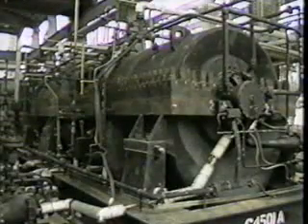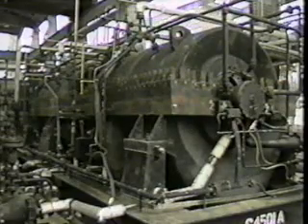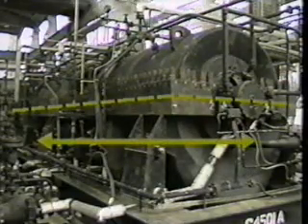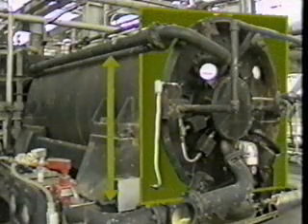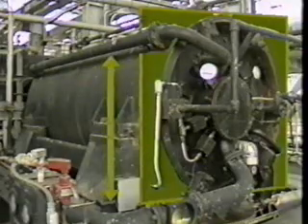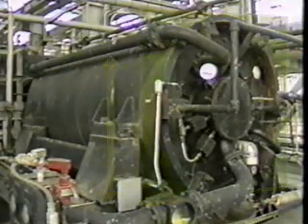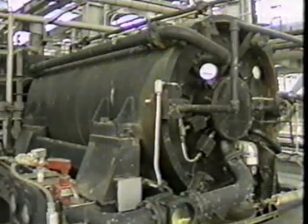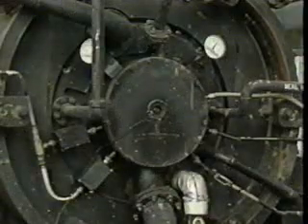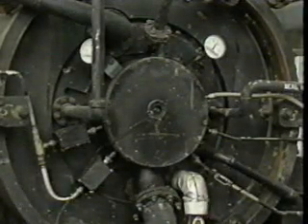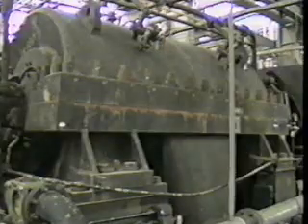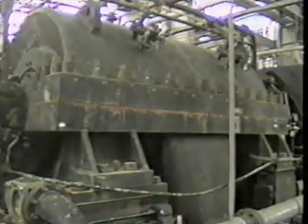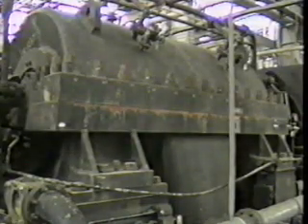In centrifugal compressors, there are two primary casing designs: horizontally split, otherwise known as axial, and vertically split, or sometimes known as radial. This split in the casing provides a means for reaching the internal working components of the compressor for repair or replacement. In addition, the material used to make the casing is determined by factors such as stress, temperature, and corrosion.